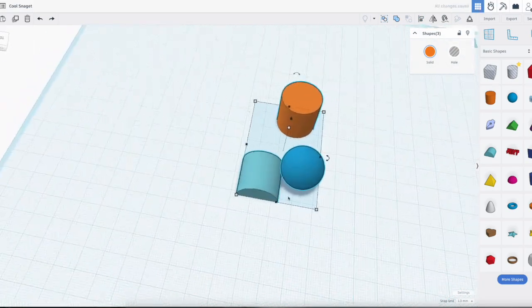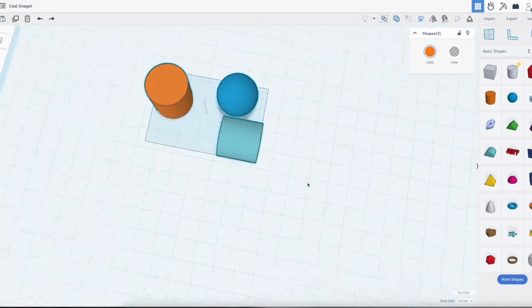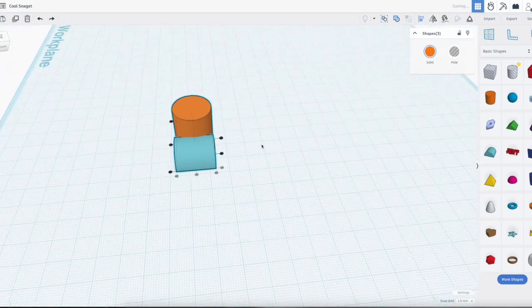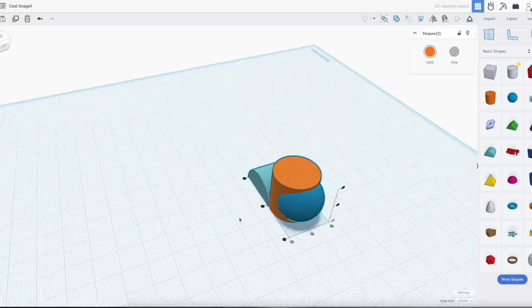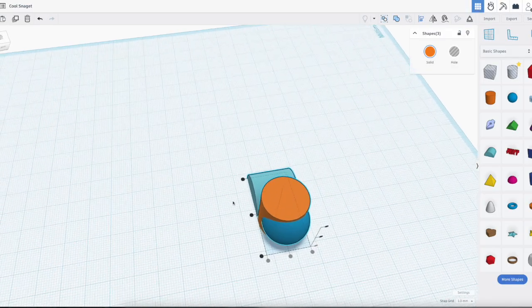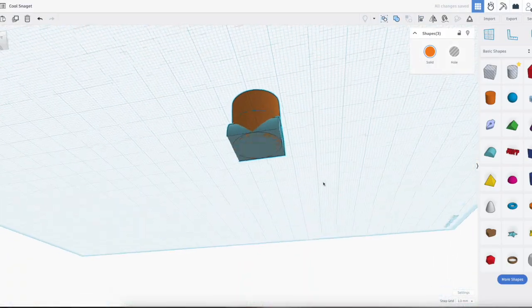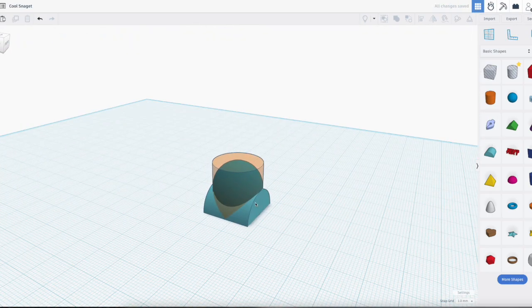If I want, hit that L key again to align them in this direction. Now rotating here, if I hover over this and click that, you'll notice they are now aligned that way. If I want them to be aligned this direction as well, where did that ball go? Well, since they're all the same size, that ball is actually inside here. If I click on solid, I can make that transparent. You'll see that that ball is hidden inside of there.